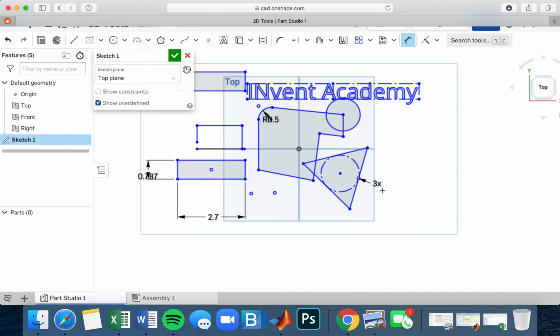Very interestingly though, you're not limited to creating dimensions only for a straight line. For example, if I want the dimension between this point here and this point here to be something, I can click on them, create my dialog box, and then I'll set this to be 4 inches, and then press enter. And there you go. It moves your point 4 inches to the left.